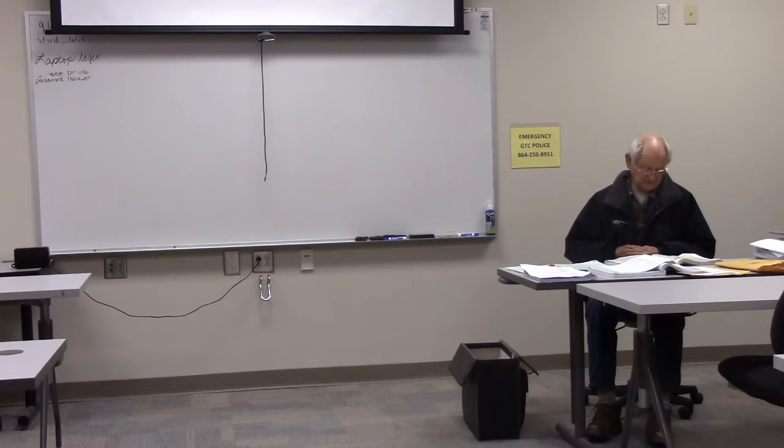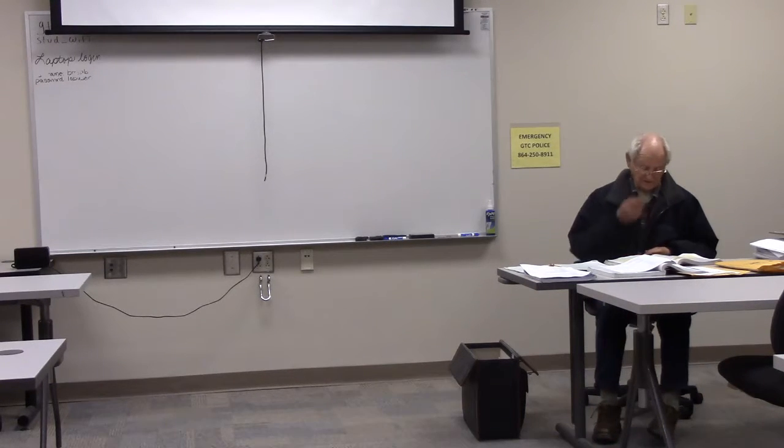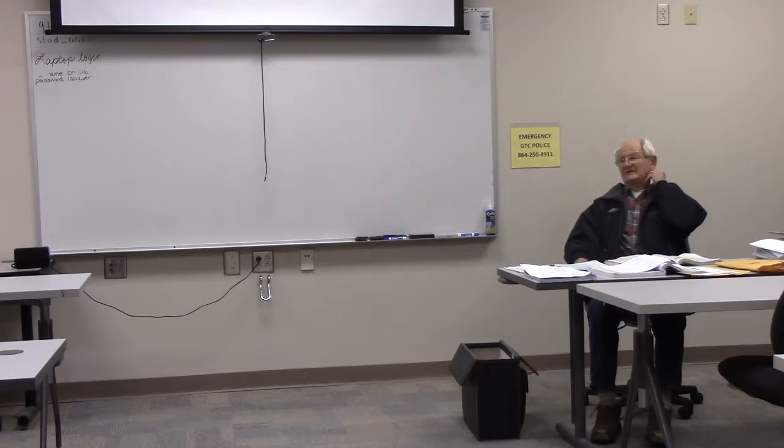So we'll have it for each scale, the measurement can represent various units derived from that scale and a multiple of 10. For example, on a 10 scale, 1 inch can represent 1 foot, 10 times 1.0, 10 feet, 10 times 1.00, or 100 feet, and so on. So if a measurement on the drawing is, say, 1 inch equals 10 feet, a half inch equals 5 feet.